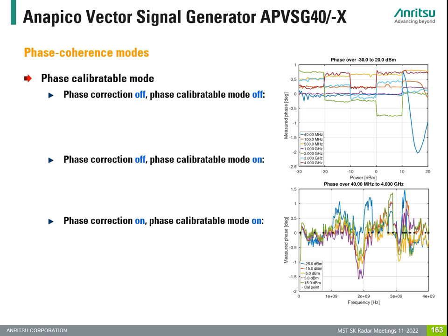The phase calibratable operation mode, also called PCM, addresses that shortcoming by using fewer and therefore larger ranges over power and frequency using a common RF path configuration and therefore generating stable phase relationships. Power setting accuracy and resolution is maintained by scaling IQ modulation data instead of adjusting RF path gain or attenuation.